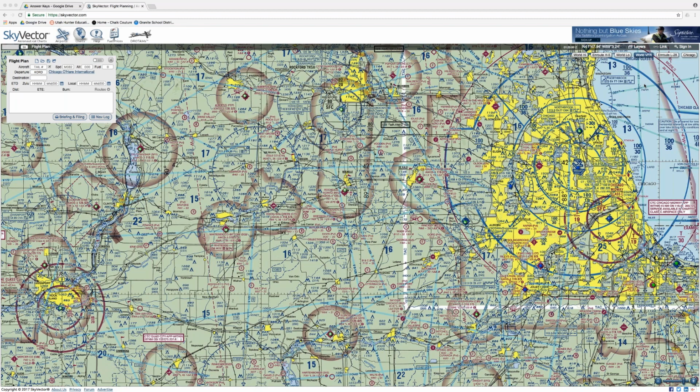I would say a ceiling, because I hear this on ATC communications all the time at my old airport, they told the pilots to report it. A ceiling would be at the point at which you're flying through clouds and then out of nowhere you can start seeing the ground. So the ceiling is right when you come out of the clouds, right above the airport at its lowest altitude, right? Layer of clouds. Okay. Gosh, I can't word it exactly correct. But there is an exact wording that you have to use. It's the lowest layer of broken or overcast.